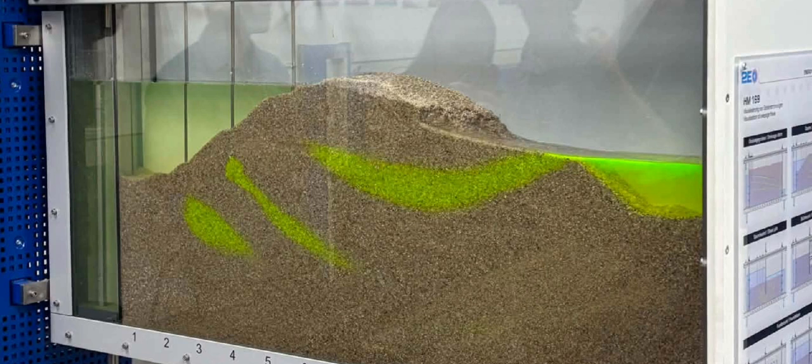2. Saturating the system, slow filling. Priming from downstream. To prevent trapped air pockets from blocking the soil pores, slowly introduce water into the downstream pool first. Equilibrating. Once the base is saturated, slowly switch the inflow to the upstream side. Raise the water levels gradually. Rapid filling can generate high internal seepage forces that cause the unconfined sand slopes to collapse before steady-state flow is reached.